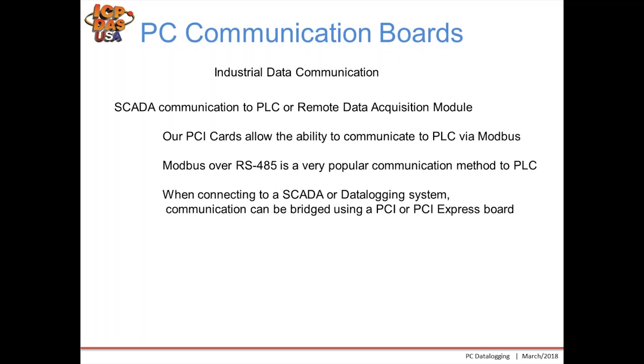Our PCI cards allow the ability to communicate to PLCs via Modbus. Modbus RTU, because it's so popular, is very commonly used with our PC communication boards. And when connecting to SCADA or data logging systems, communication can be bridged by using a PCI or PCI Express communication board.